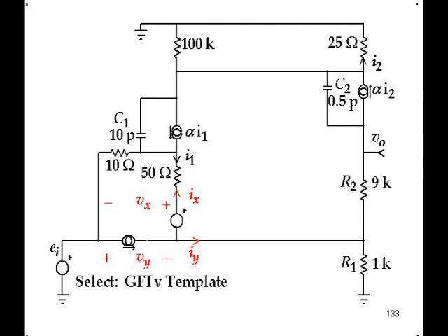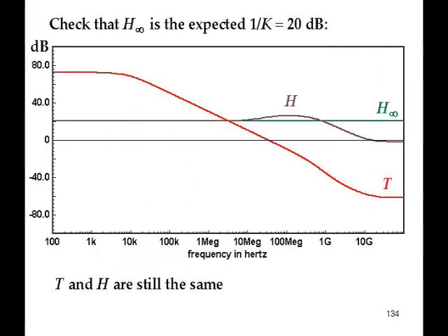And all of the techniques and all the stuff I've talked about today and all the stuff that's been written for umpteen years beforehand, it's all the same, whether they're BJTs or FETs, except for that one tiny difference. Okay, here's the results of the simulations of that model with the coupled injection at the error signal summing point. H infinity is flat at 20 dB where we wanted it. The loop gain has 2 poles and the right half plane 0 where it should be.